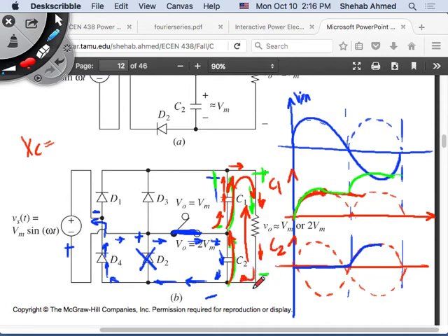It has to charge in one cycle, discharge in the other. So capacitor C1 was charging in the first half cycle. So in the second half cycle, current will have to be going in the opposite direction. And it cannot go in the opposite direction back through the diodes, because these diodes are all pointing up. So it's going to go in the opposite direction through the resistor.